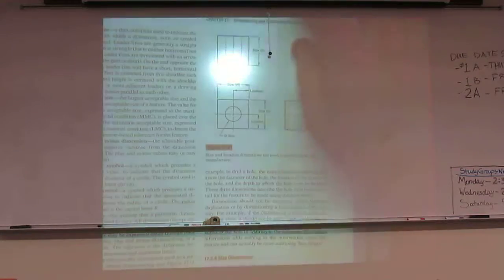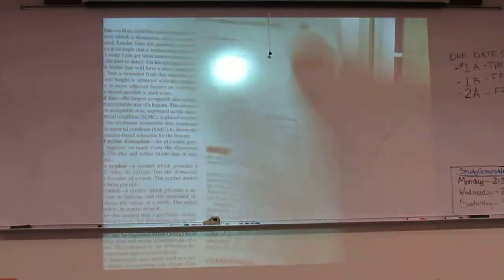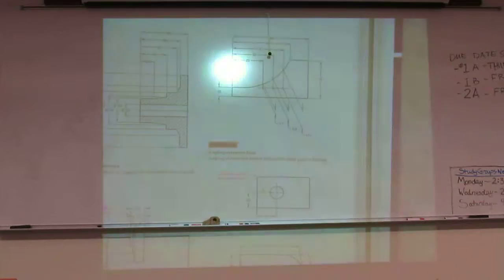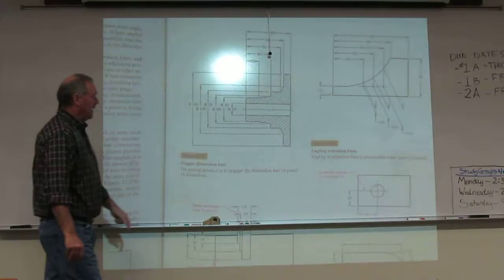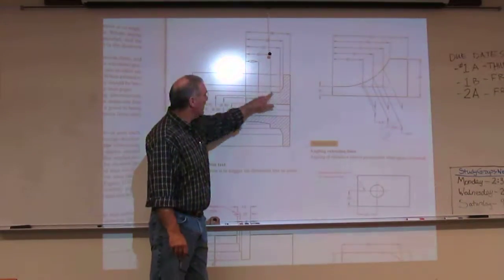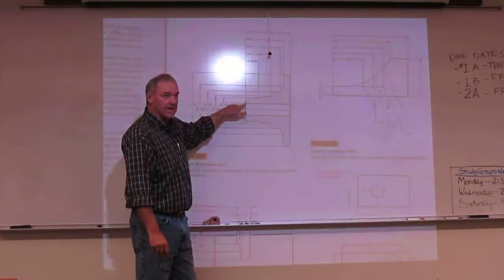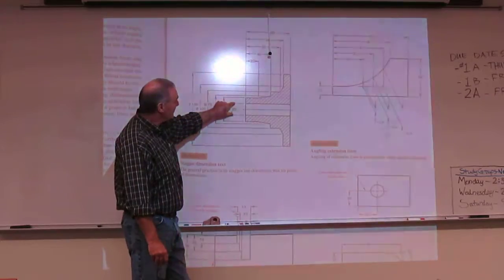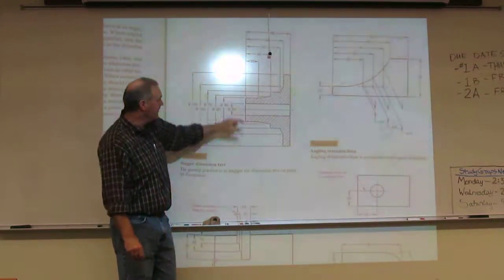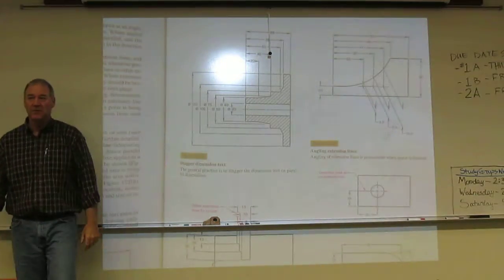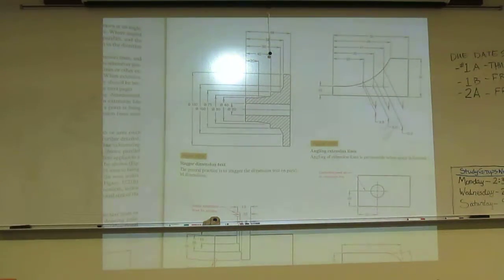Let's go to figure 17.17, which is this one. Here you see I've got a negative cylinder and then all positive cylinders. So this negative cylinder would normally be done in the circular view. Here we're going to do it in the rectangular view because it is in section.